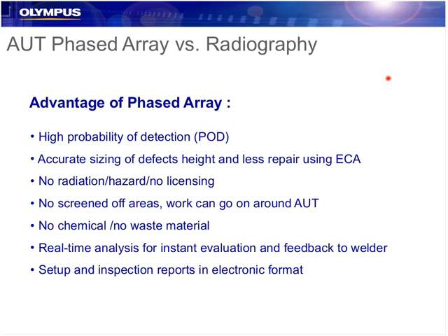We saw the strip chart recording. We'll see that a little further in the slides and maybe actually in the program itself. Based on the strip chart recording, we're able to quickly see if the weld is good. This is really critical especially offshore, because often as soon as the pipe is inspected, they want to be able to take the pipe and install it underwater. And even onshore, we want to keep up with the welding process. We don't want to be too many welds behind.